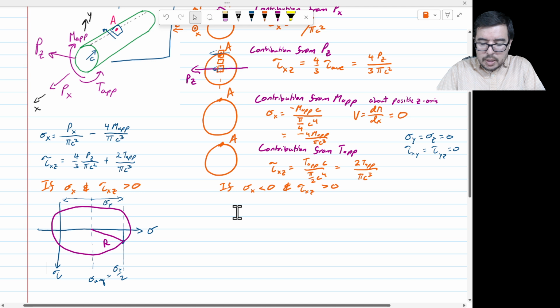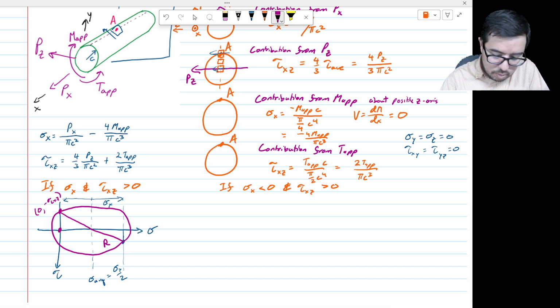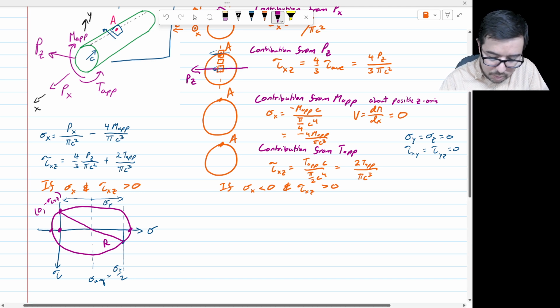But what do we know the maximum shear stress is going to be for this system, right? Because that's what we're looking at. We know that we had this, it was over here, right? So this point right here was 0 comma minus tau xz, all right? And given that the rest of the states of stress are 0, we're going to be here, no less. So this could be your sigma 1 here, this could be your sigma 2 here, and this could be our sigma 3 here. And the Mohr circles are going to be something like what we're showing. And again, these are very distorted. They're more like Mohr's ovals, okay? And so the absolute maximum shear stress is going to be down here, all right? It's the radius. Now, what's the radius?